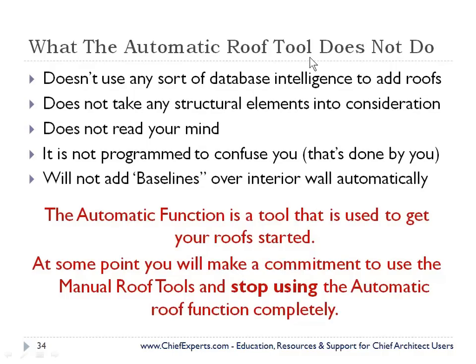What does the automatic roof tool not do? It doesn't use any sort of database of intelligence to add roofs. None whatsoever. What I just showed you is the only thing the automatic roof tool does. Puts a baseline on. Again, that baseline height is determined by the ceiling height of the room next to the outside wall. It does not take any structural elements into consideration.